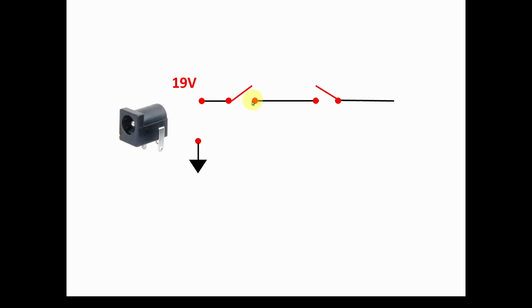We mentioned that before. When we plug in or remove the DC from the input jack, we want to be able to switch that 19 volts going into the computer on or off based on those different considerations. So we want some controlled switches right after we plug into that input jack, right?